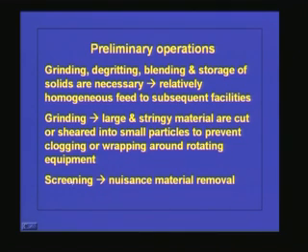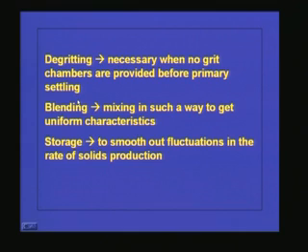So this grinding is essential for the screenings. The screening will remove the nuisance material coming after grinding, and also some floating material which is larger in size and not ground properly. That will get removed in the screens. And in degritting, if you do not have a grit chamber, or if the grit chamber is not functioning properly, then definitely this inorganic material will come along with the biosolids.